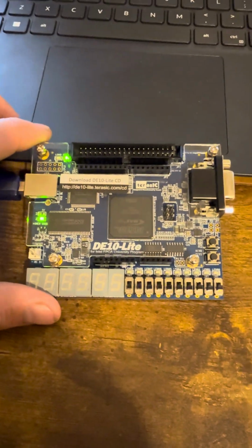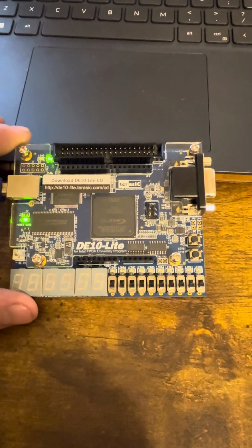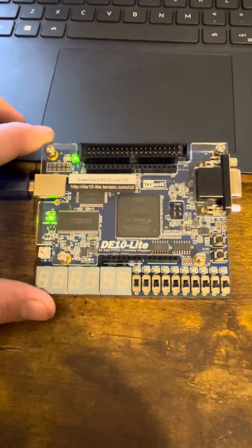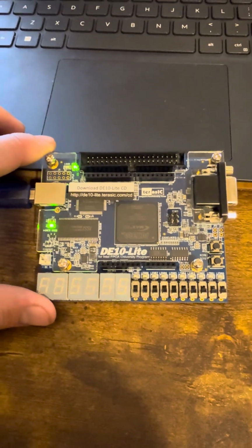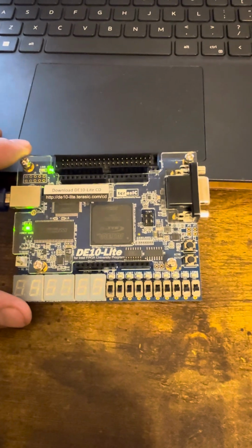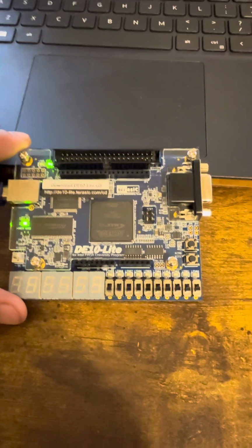What we did in this lab is we built 4 2-to-1 multiplexers. A multiplexer has many inputs and one output, and you use control signals to select which input you use for your output. So in this situation it's a really easy version.